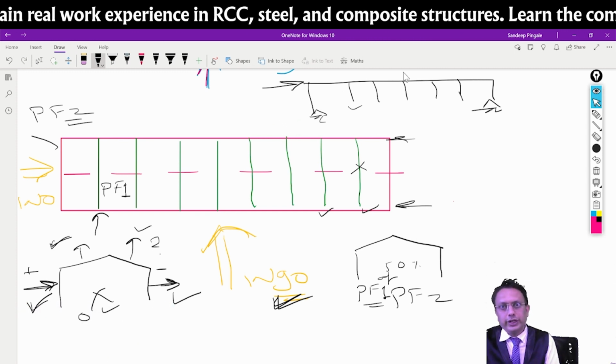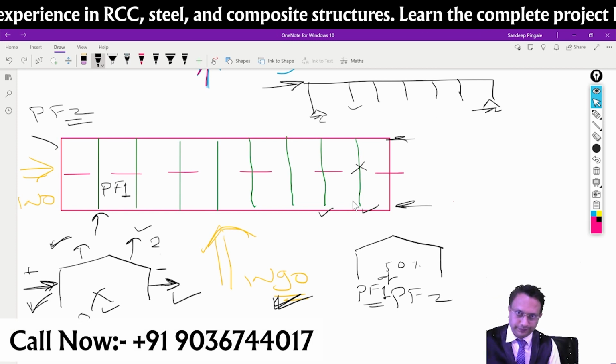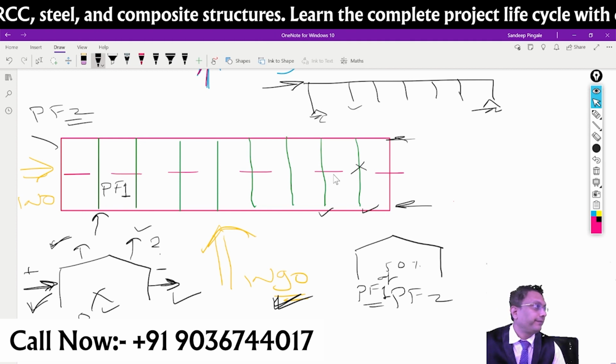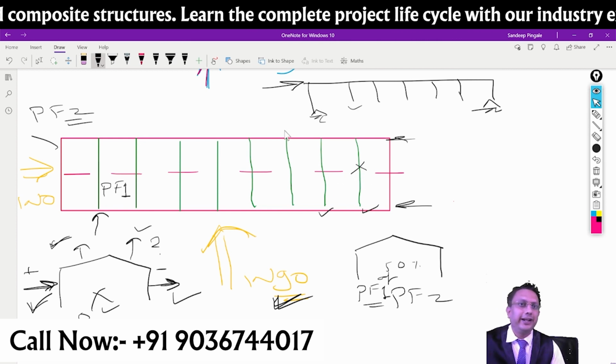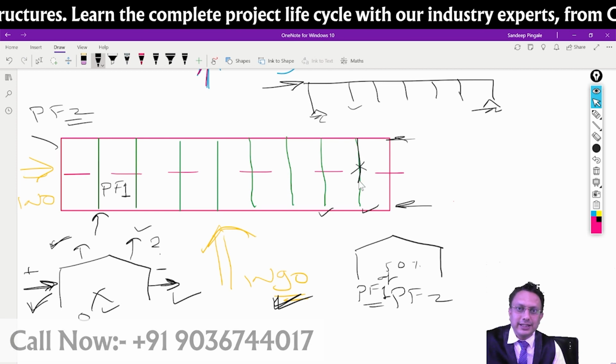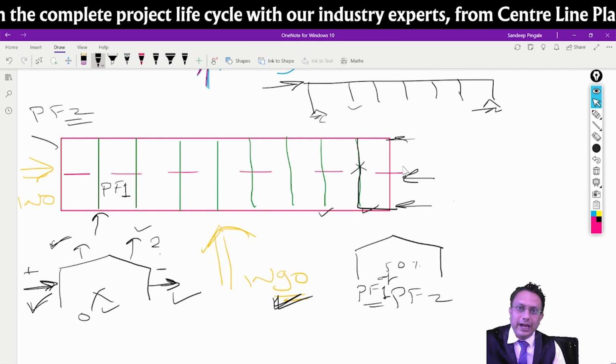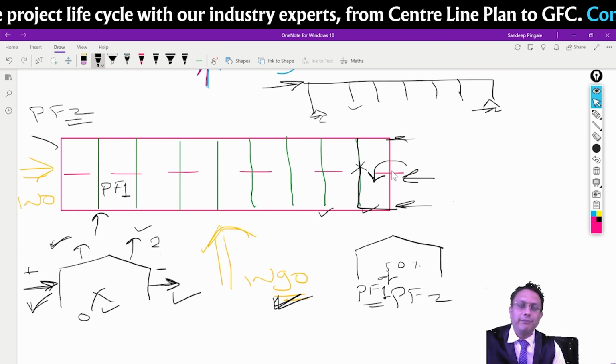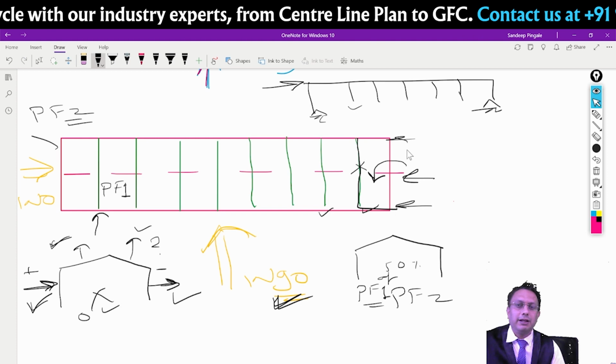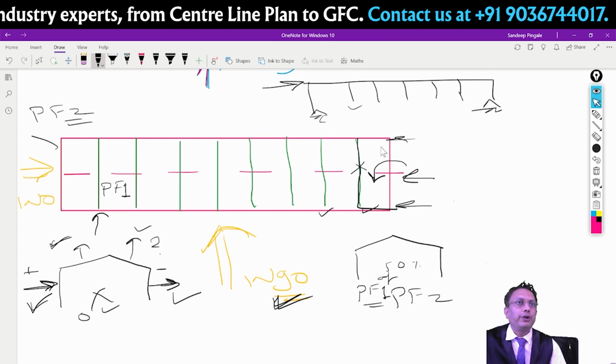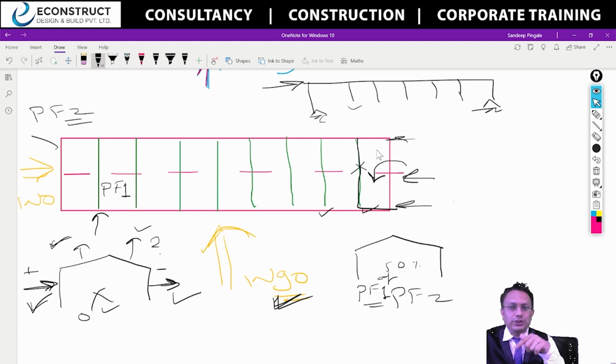So are you going to take it full as one force, one truss? No, because it is uneconomical. Economy is the basic principle in India. So you will say, I will apply the force and make sure it goes from the structure to the sheetings, to the purlins, to the roof sections, then through the cross bracings to the columns and to the foundation. It will not go in this direction. It will go directly from here. I will make sure that it is transported down.